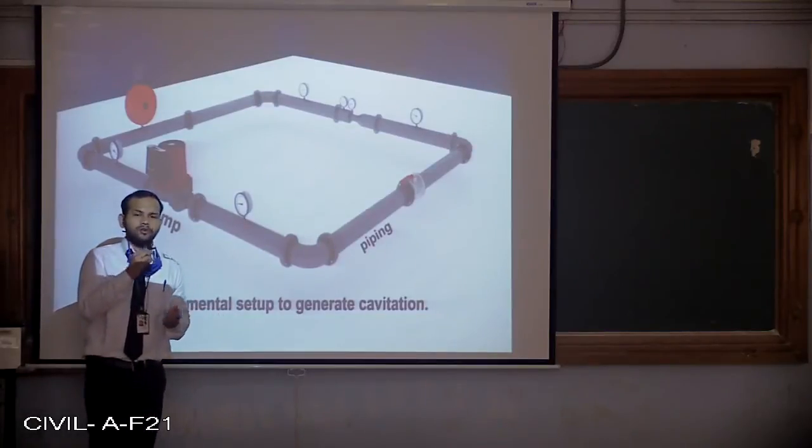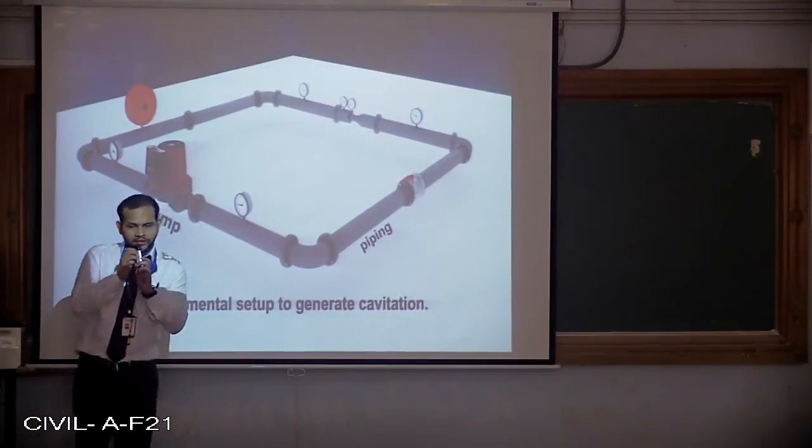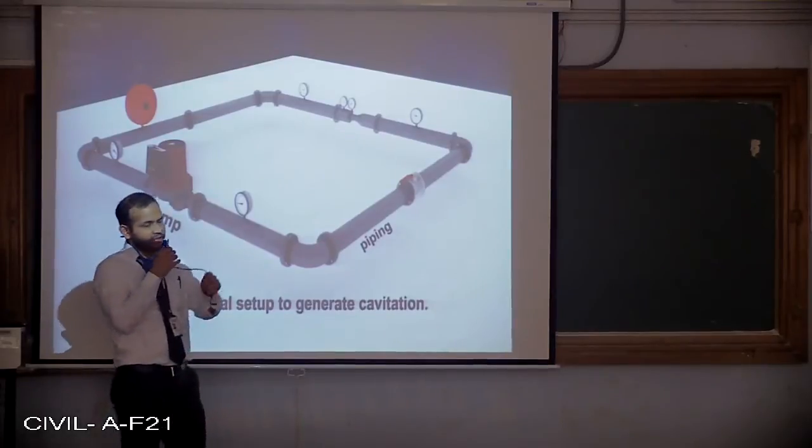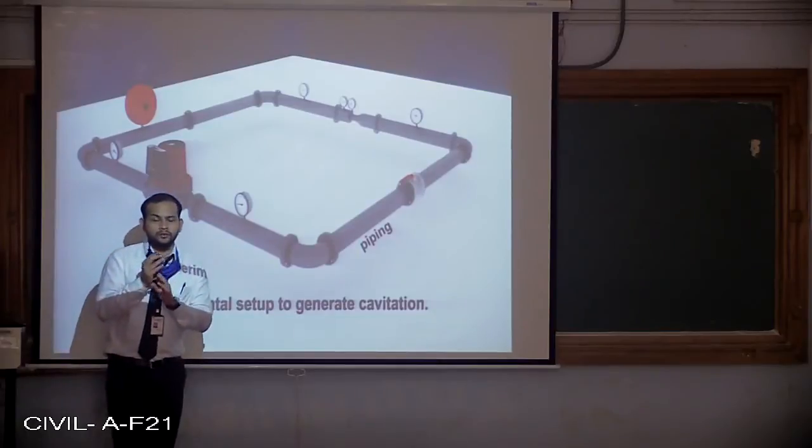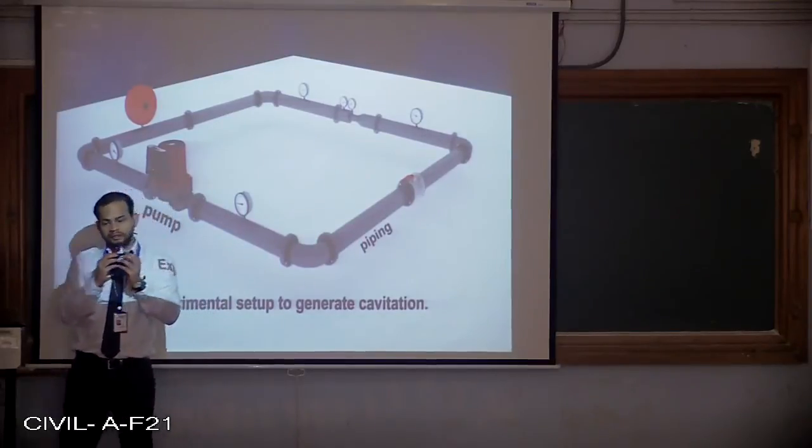That will cause rusting of your pipes. So as an engineer, you have to design in such a way that there is the least cavitation occurring. And if not, you have to choose a material which can resist the cavitation phenomena.